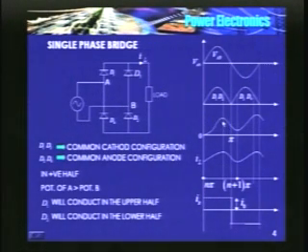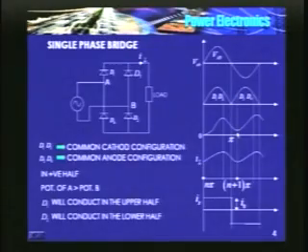In the positive half, current reaches maximum somewhere in between pi by 2 to pi. It starts decreasing. Depending upon the load parameters, it continues to decrease, and again it starts increasing in the negative half cycle. And at the instant when the current starts increasing, the KVL is Vi is equal to I min into R. I will repeat, at this instant Vi should be equal to I min into R, whereas here it is Vi is equal to I max into R.